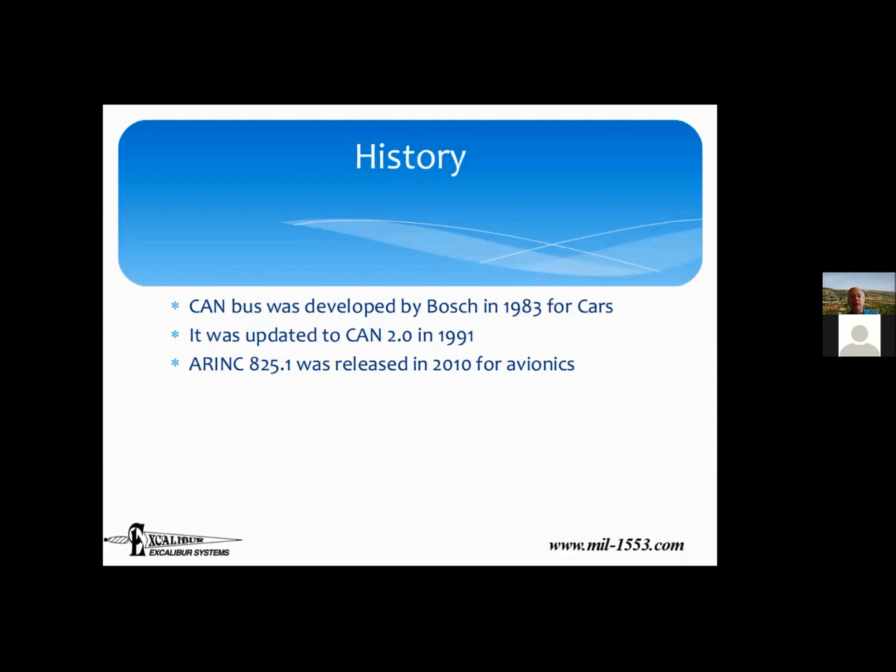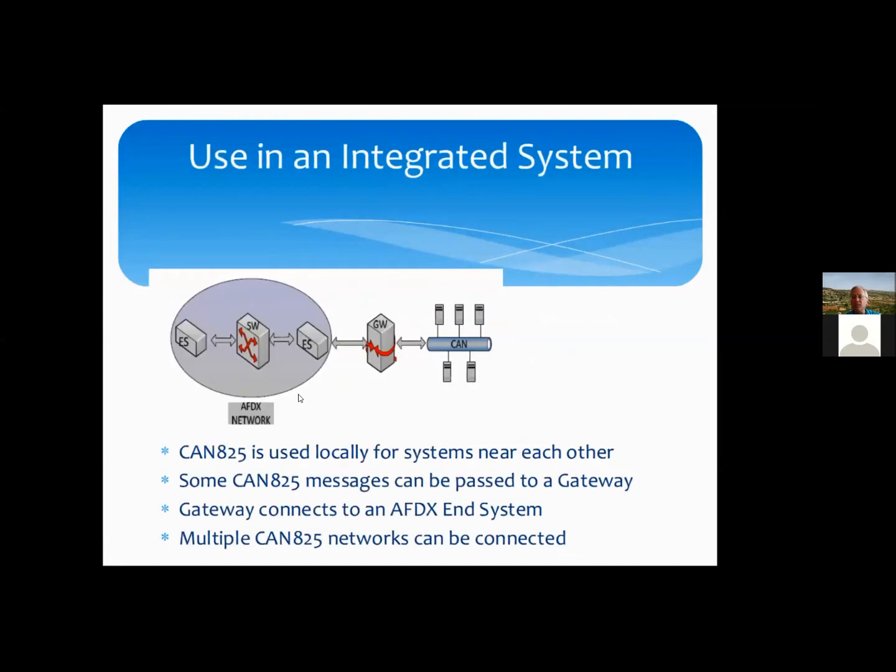We're now up to ARINC-825.4, which was just released like a year or so ago. The major difference is that 0.4 deals with a faster speed for CAN Bus. It's not yet in a great many implementations, so I'm going to be focusing on the more standard low speed, which gives you up to 8 bytes per word.